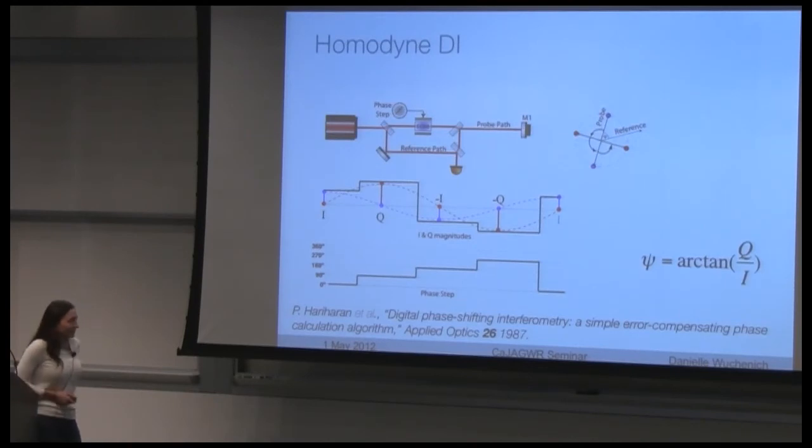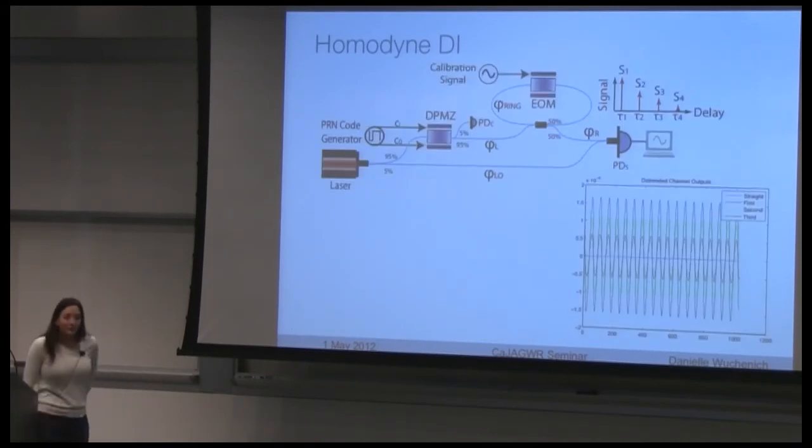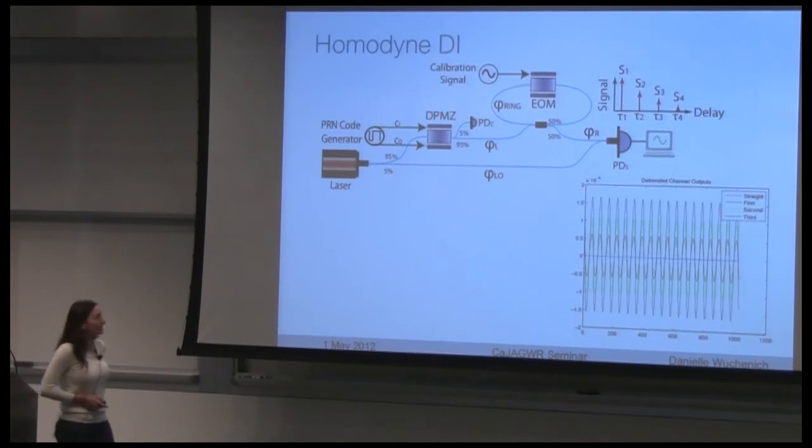And you can still get phase recovery even without this local oscillator. One of the PhD students in my group is working on this, Andrew Sutton, and he's just getting first results. Basically, he has something that does the PRN encoding with the QPSK. So now it's a 4-stage modulation as opposed to the 2. Instead of just the 0 and pi, you now have 4 elements in the constellation.